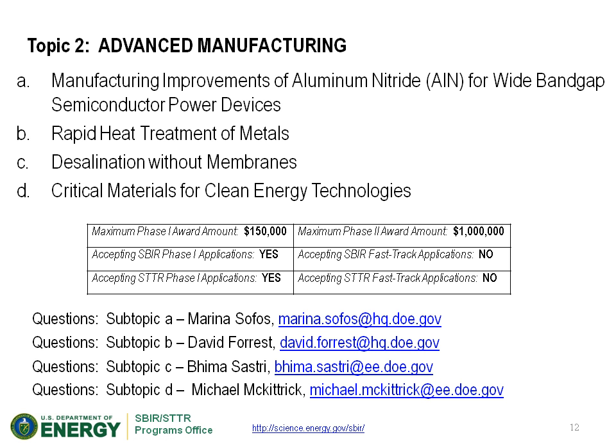If you have a continuous, for example, annealing line that is typically 100 or 150 meters long, technology such as induction heating can heat that material in a much shorter length, on the order of a few meters instead of 100 meters.